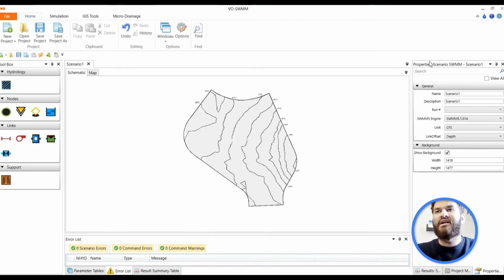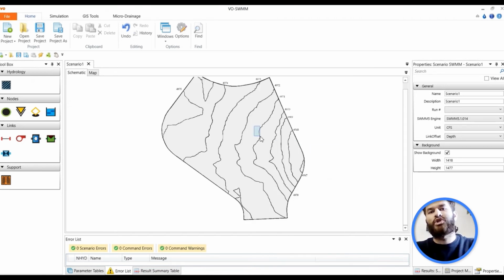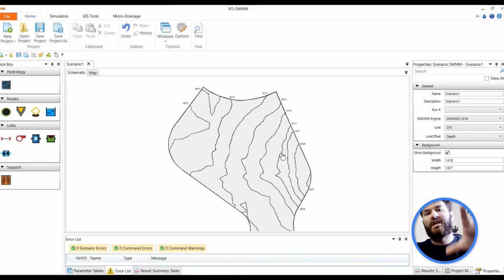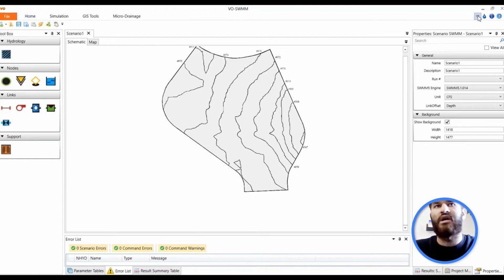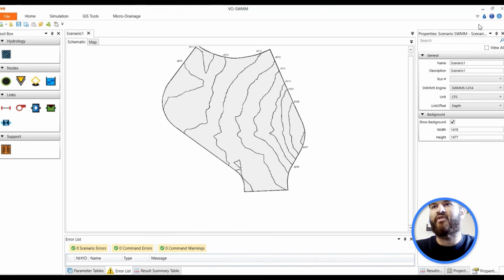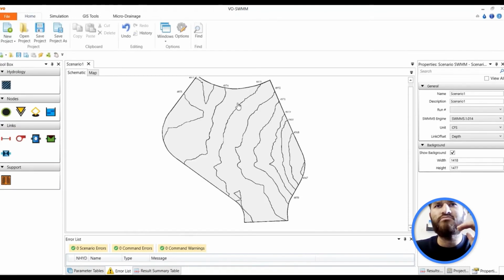If you want to zoom in, or if you want to better understand or visually see your area, you can either hide different parts or just shrink different ribbons around the pages. So this is the background picture that I have. All I need to add is a subcatchment or a catchment feature to this part as a representative of my catchment, and an outlet on the southeast of here.